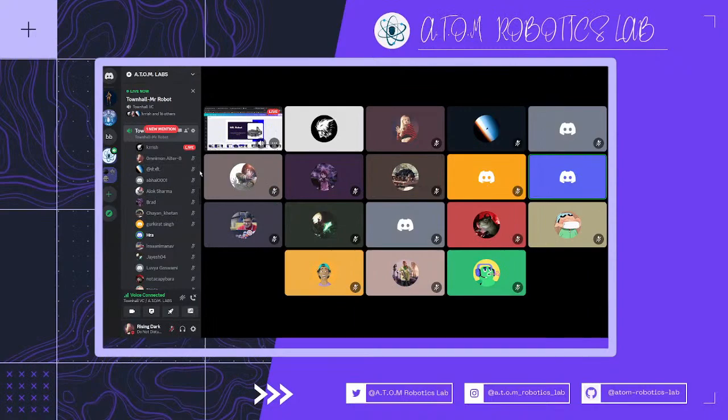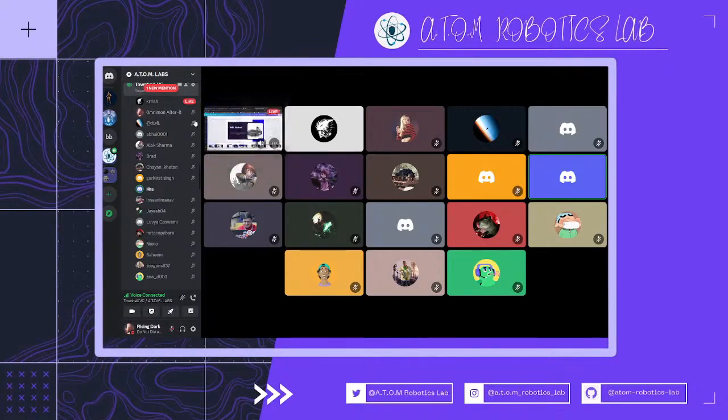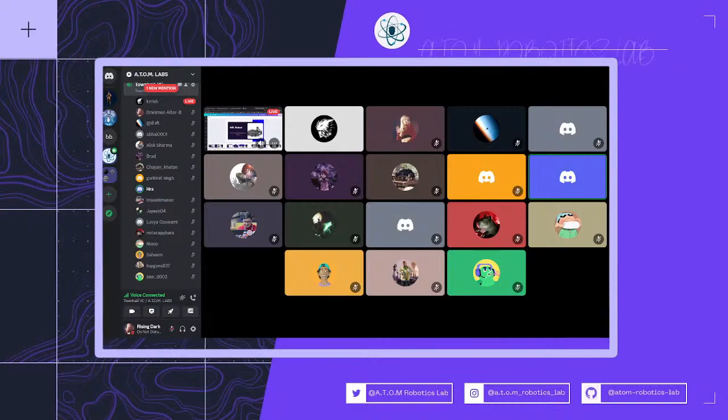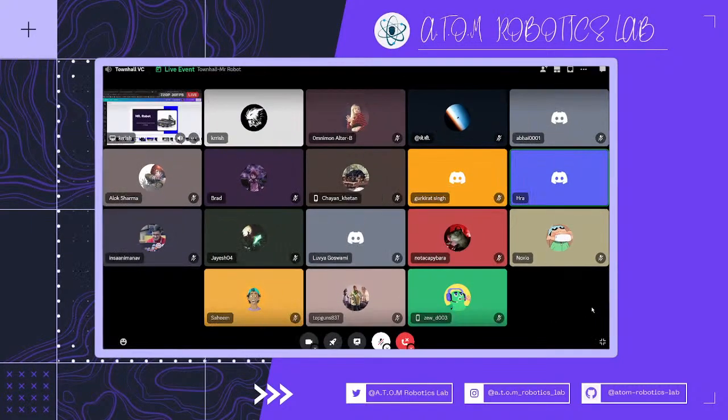Right now, for our project, we are using a Kinect for the 3D mapping part. The IR sensors inbuilt in the Kinect, along with the depth sensor, provide us with the 3D visualization of the arena. And yeah, we perform octomapping using the Kinect sensor. There is a ready-made package available for the Kinect sensor with ROS, so right now we are using that.